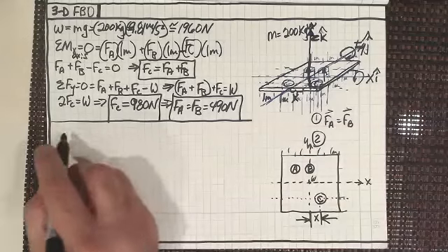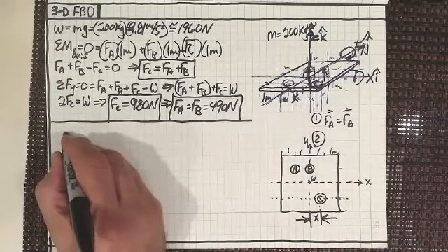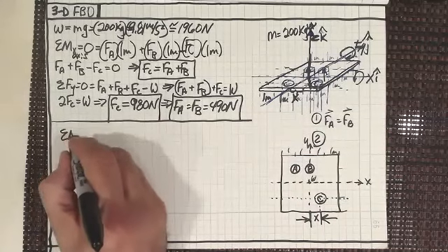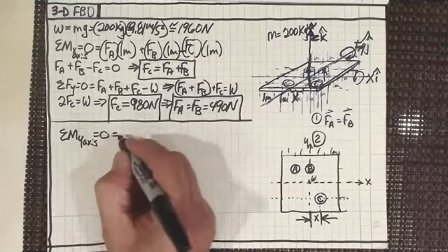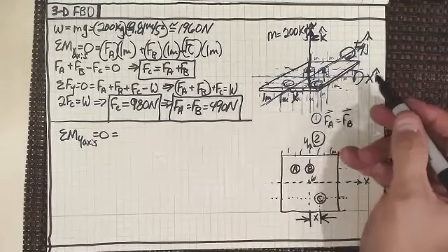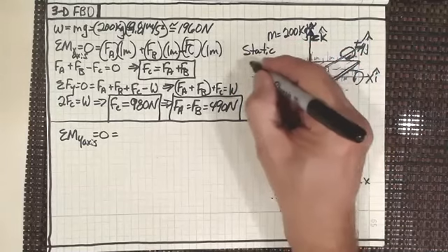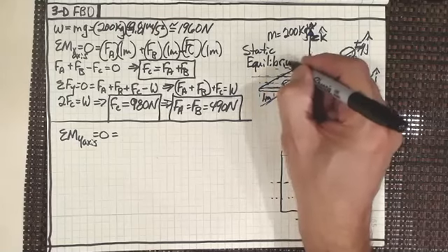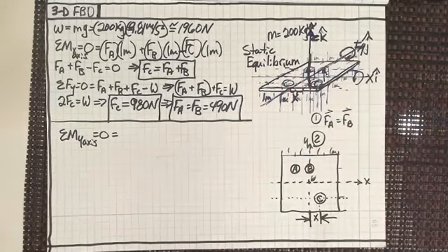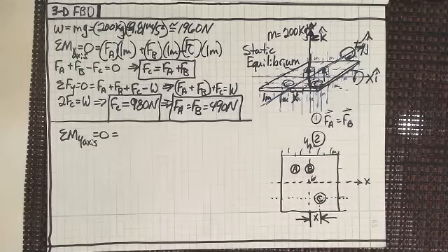So I've got C times 1 times whatever x is when I'm summing moments about the y-axis equal to 0 because there's no rotation, no movement at all, right? We have static equilibrium. And that's what I'm using. I'm using the analysis of static equilibrium, right? Summation of the forces in the x and y direction equals 0. Summation of the moments equals 0 about any point or axis. That this is giving me the information that I have.